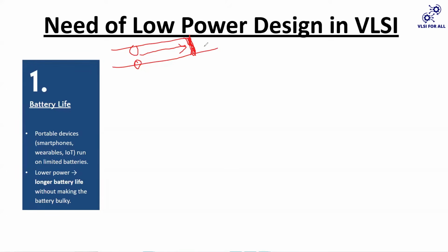Before this, what can happen is, once this is opened up, there are no particles over here. So this will create an open over here. In terms of VLSI, it is called an open, and this is called a short. This is even called an open or void. And this is called a hillock, because it is kind of like the upper layer. Why it's called a hillock is that there are two hills which have locked each other. So this is the terminology called hillock.